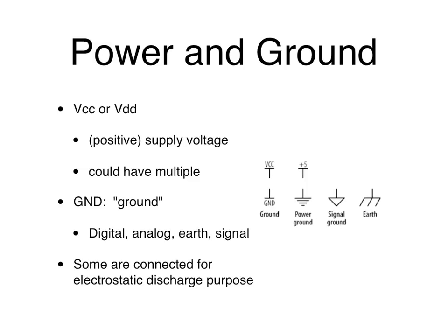When you have the GPIO P0, P1, each one actually is a signal. A signal is trying to convey some value. It could be an analog signal or a digital signal, but it's conveying a value using its voltage. It's not meant to be a source for driving a light, an LED, for example.